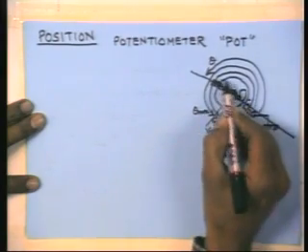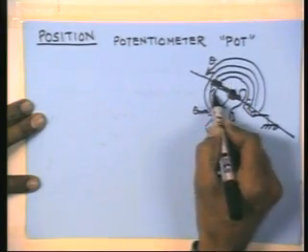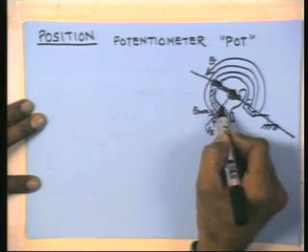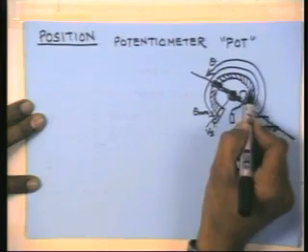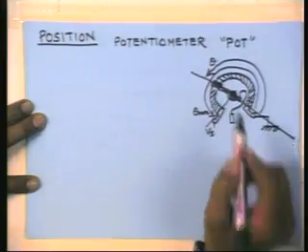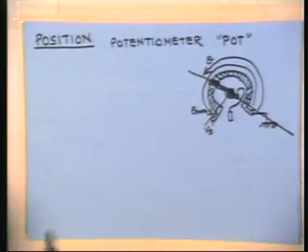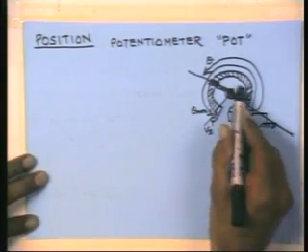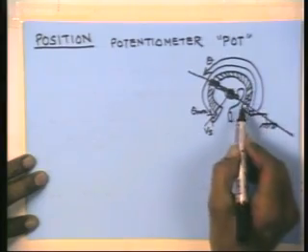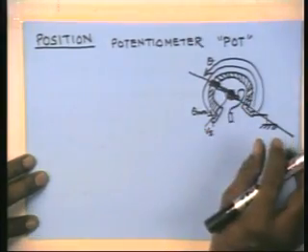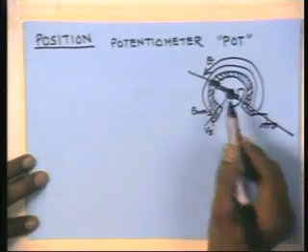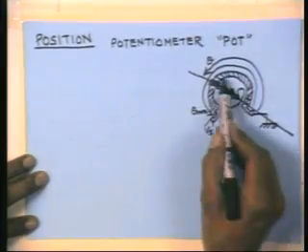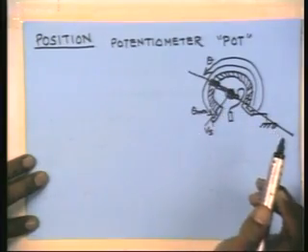So let me shade this also, because now my angles have cluttered up the picture. So this is the resistor film. This resistor can basically be a wound wire. You take a fine wire and you wind it in a coil, and then you make sure the top surface insulation is removed, so that when the wiper moves on it, you can have the flow of electric current taking place here.